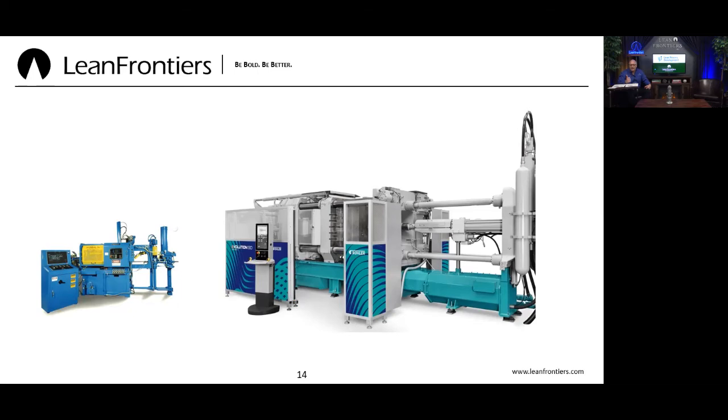So 1/10 the capital expenditure. Also, that means the tooling is going to be less because you've got a much smaller die that goes into it. The changeover, instead of climbing up on this machine, needing some big crane and all the complication with it, the die is much smaller. It's actually right at a person's height. So all these parameters you need for a one-piece flow, for a less capital cost, for if you want to do a Kaizen line, moving it around becomes much easier. Moving those die-cast machines was very expensive and difficult. So all these parameters were in play.